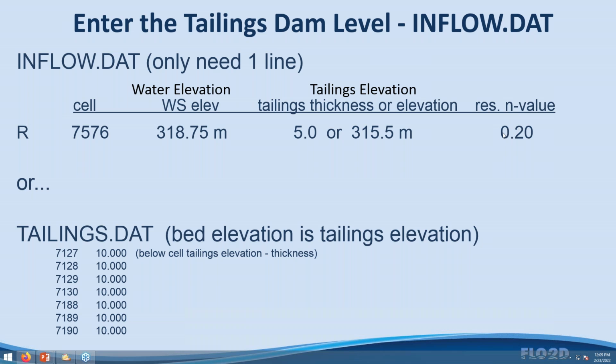But I just use a base value of 0.2 here for the reservoir, and that's so that you can route flow using the Manning's equation in a ponded situation in a reservoir, because you don't have a turbulent velocity distribution profile when the water just starts to move initially, and so there's no way to get 1 foot per second average velocity in the vertical profile if you've got 20 feet of flow depth in the reservoir using Manning's equation, because what you're going to wind up with, unless you use a high enough N value, is something on the order of 50 feet per second right off the bat, and the water's just sloshing around in the reservoir.